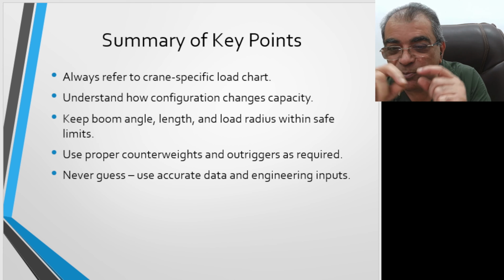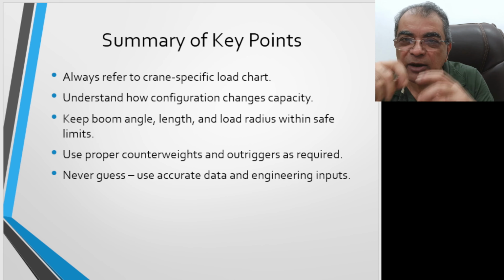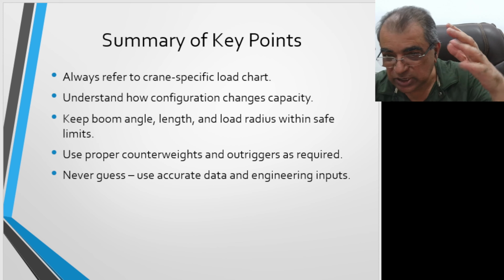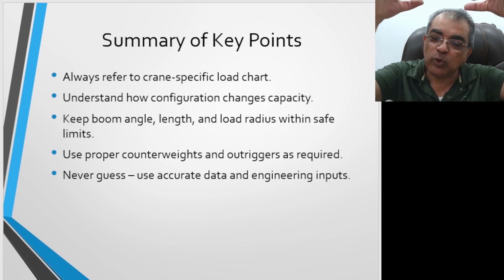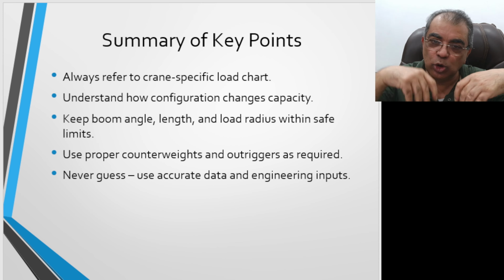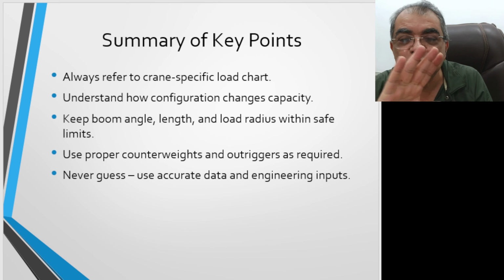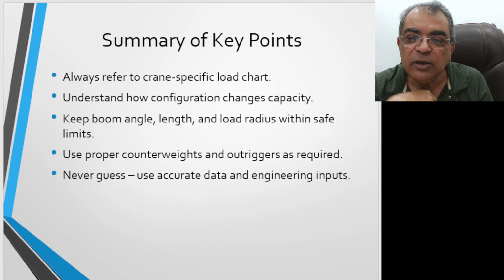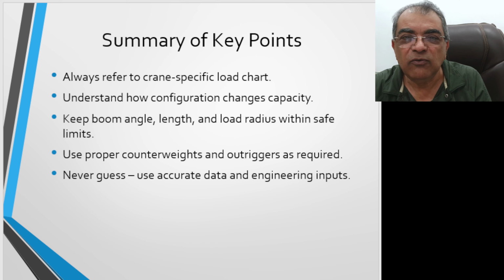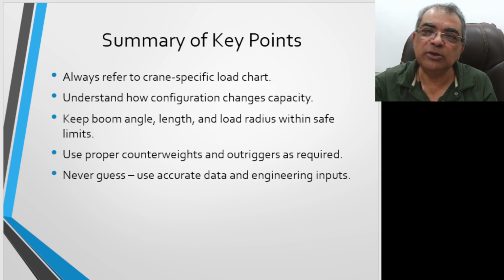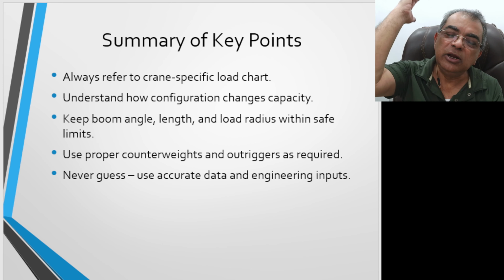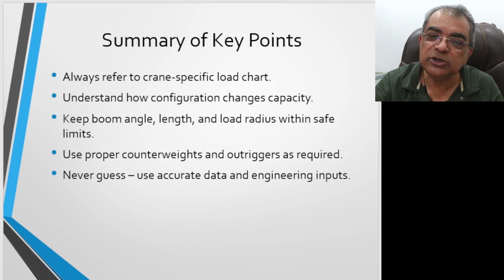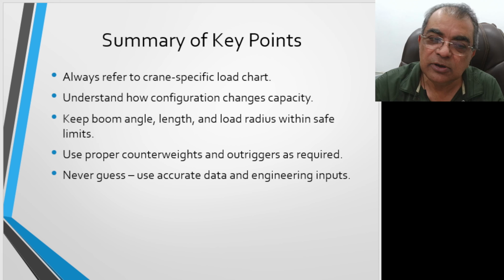Some people are playing with this. They are doing something else. If it is stationary, then you have to anchor it with more loads. Never guess. Use accurate data in engineering lifts, because it has happened to me. I have witnessed one accident when, under pressure, they tried to lift unnecessarily beyond the crane's capacity, and it became a fatal accident.